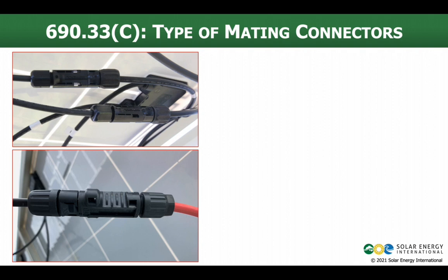I see this all the time doing inspections, where I see connectors either put together wrong or matched up with connectors they don't really mate with. The problems, as you can imagine, often result in increased resistance in the circuit from connectors that don't plug together right. Maybe they let moisture in, which creates corrosion, creates resistance, creates heat.